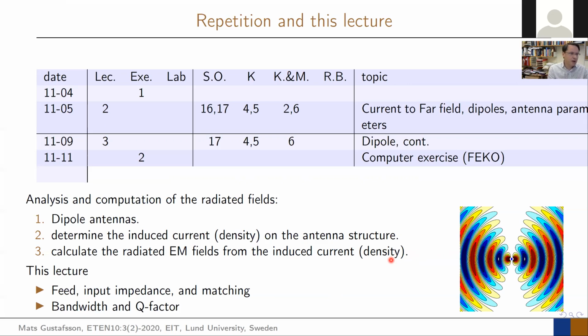We looked at this time delay that you have from different positions of the antenna to the far field, and we also interpreted the removing of the radial component of the radiation vector as a plane wave which propagates with E and H perpendicular to the direction of propagation, and the direction of propagation is in the radial direction.